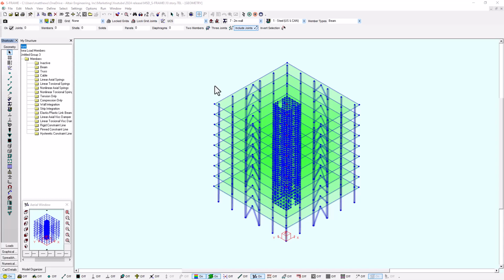For a bit of background, the Multistory Designer is a utility within S-Concrete that facilitates the import of concrete section data, the associated loads and positions within the structure, into the S-Concrete Multistory Designer that helps facilitate the assignment of reinforcement on a global basis that can be refined on a section by section basis as well. It can do the code checking at both a high level and detailed level, just like you would out of a regular S-Concrete design. And it can generate S-Concrete files for your entire structure, as well as produce detailed engineering design reports, schedule-like reports, and more. So we're going to look at how that can be done.